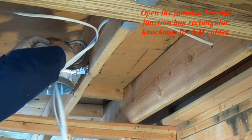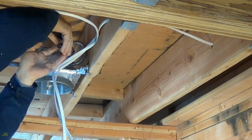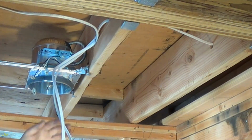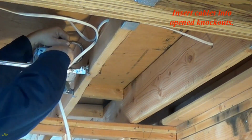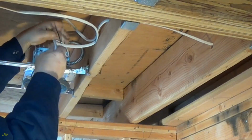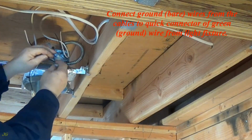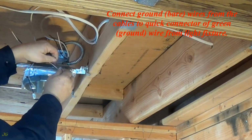Open the junction box and junction box rectangular knockouts for NM cables. Insert cables into opened knockouts. Connect ground, bare wires from the cables to quick connector of green, ground wire from light fixture.